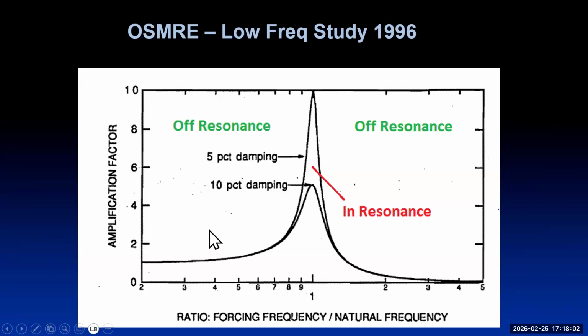And Alan can speak at length about that and it's on YouTube. But when they do align, it is, as Alan said, 1/2 zeta. And if you have 10% damping, you can get 5x on the amplification. You have 5% damping, you can have 10x. As Alan said, on structures, let's call it 3 stories and up, on 3-story unreinforced masonry structures, we'll see 3, 4% damping. So you've got the potential of 12, 15 times amplification if they perfectly align. If you've got 1% damping, as Alan said, you can have 50 times amplification. Now, that's on perfect alignment.